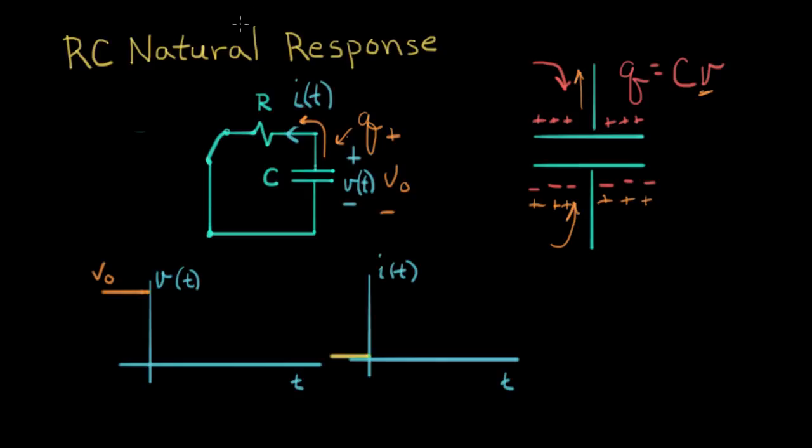So we can draw that. What we're going to say is after all this charge rushes out of here, goes through the resistor, and ends up on the backside of the capacitor, neutralizing the charge in the circuit, that means the voltage in the circuit is going to be 0. So we can draw that. We draw the long time from now out here. It's going to sketch in as something like that. It's going to be low. Likewise, the current is going to end up at 0 when we're finished here. And that's what happens with every natural response. Basically, the energy in the circuit is allowed to die to 0.